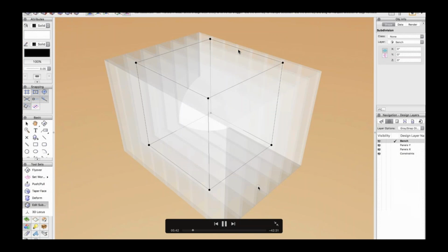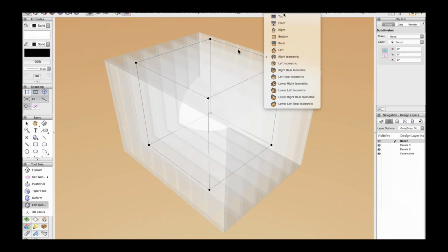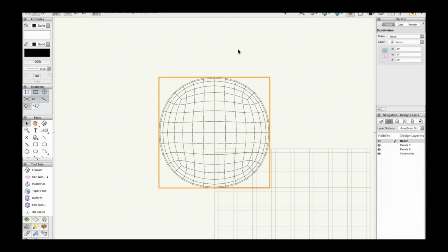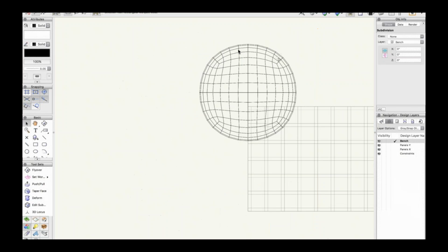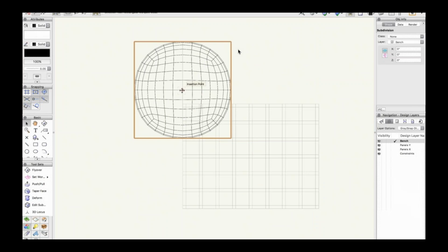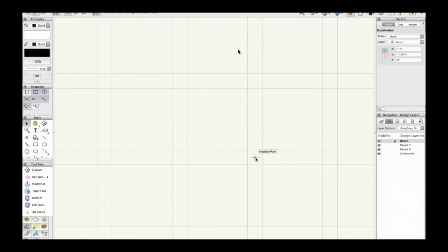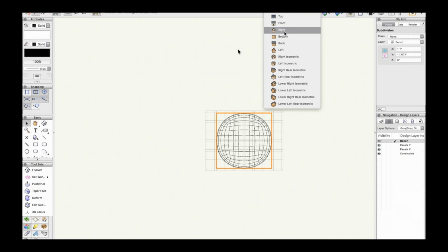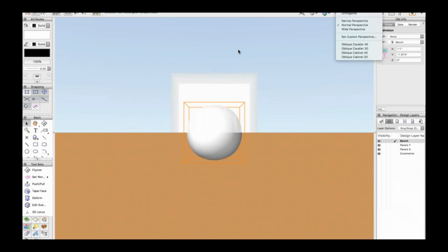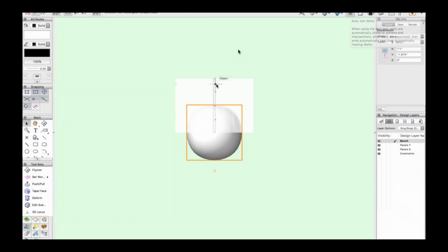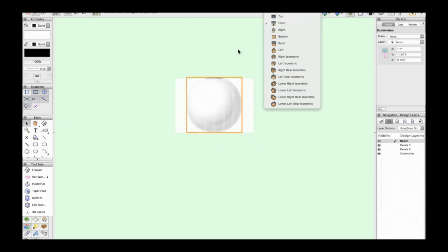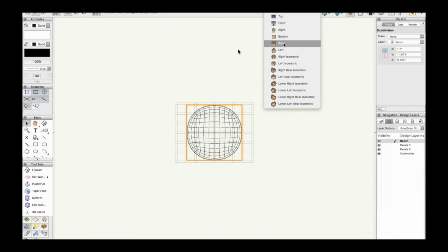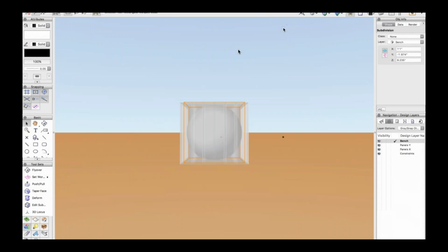Well, I selected a sphere from the drop-down menu, and when you park a subdivision object into your design layer, it places it at your 0, 0 origin. Well, the grid that I had created previously had started at the 0, 0, so I have to actually move that sphere to the center point of the grid that I've created. So what I'm also checking here is that it's on the same horizon. Well, also notice that when you create subdivision objects, its insertion point is also at the 0 as far as the Z goes. That means that half of your object, if it's a subdivision object, actually appears below your horizon.